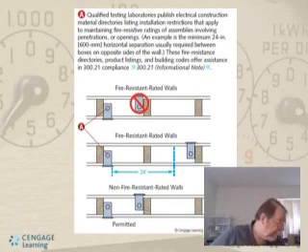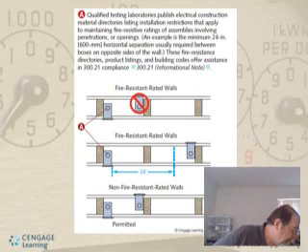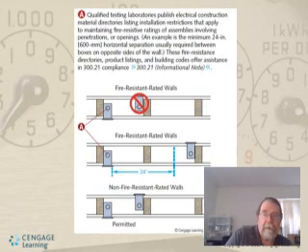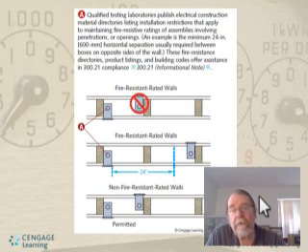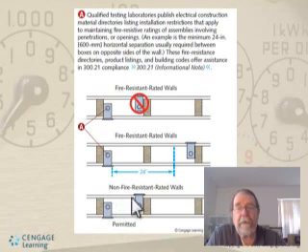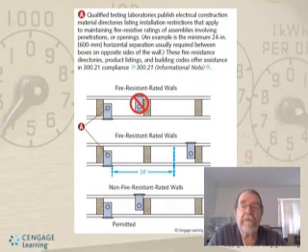Now here we're getting into fire-rated walls and back-to-back receptacles in the same wall. Essentially, you can't put them in close proximity in fire-resistant rated walls. You need to separate them, and it's got to be at least 24 inches. Now, in non-fire resistant rated walls, which is the third image here, you can put them in there. This is regular sheetrock. And that's explained in 300.21.